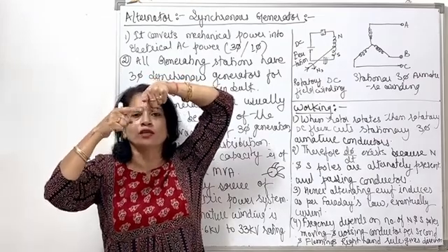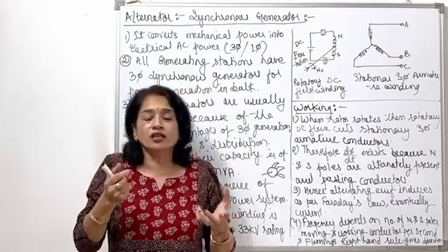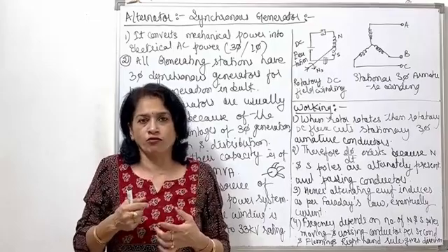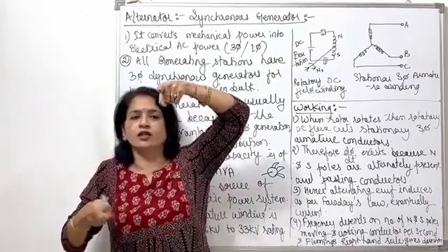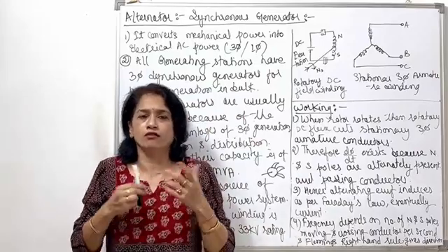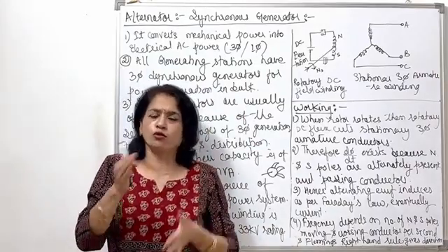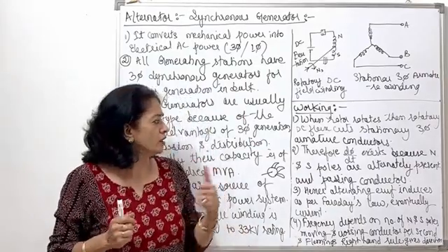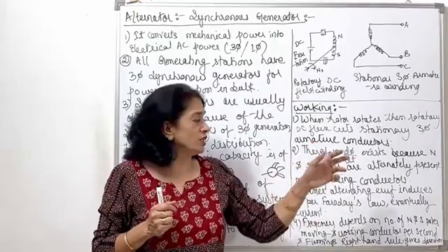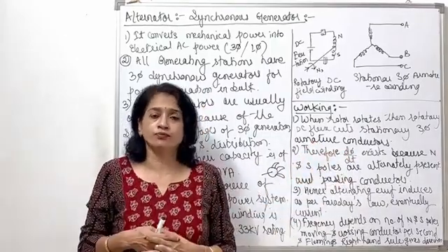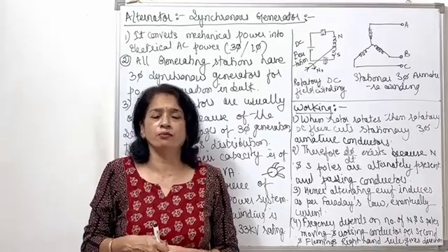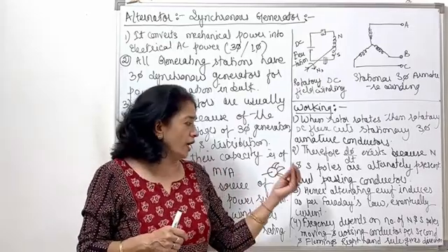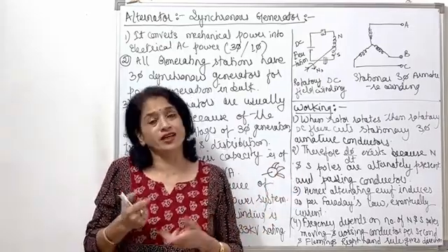So with respect to the conductor, there is a regular periodic variation of flux cutting it. An individual conductor is cut by flux first from the north pole, then the south pole, then north, then south, likewise. With the rate of change of flux, according to Faraday's law, EMF is induced, and that EMF would certainly be AC.